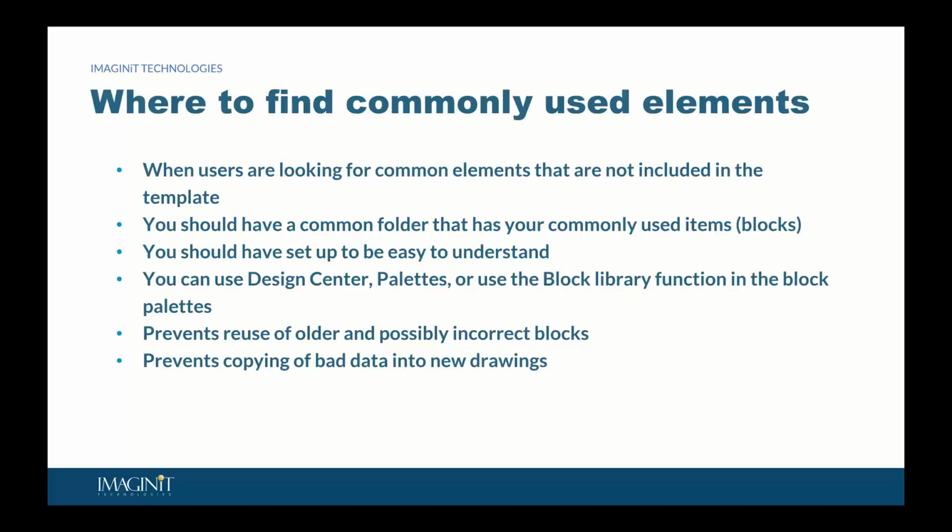If there's a problem in the drawing they're copying from, that problem is going to get copied into the new drawing. If that drawing was from an older version of Civil 3D, it can cause untoward issues and can create other elements and other issues inside the drawing you're in. So we want to try and prevent all of those things from occurring by creating this blocks library, and again, we want it to be very set up and make sense.